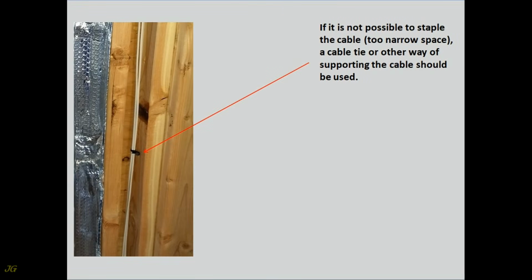If it is not possible to staple the cable, for example in a too narrow space, a cable tie or other way of supporting the cable should be used.